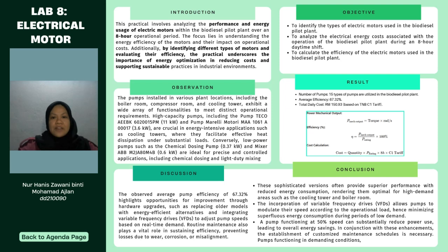For the discussion, efficiency can be improved by upgrading to efficient motors, using variable frequency drives, and regular maintenance. For the conclusion, prioritize efficient motor replacement using VFD for speed control and energy saving, and last but not least, implement regular maintenance for optimal performance and cost reduction.